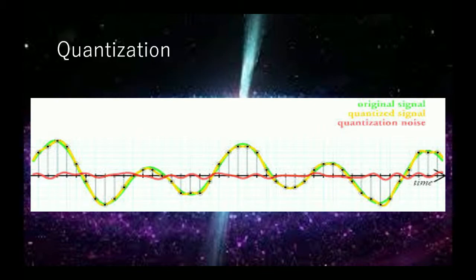There are two types of quantization: uniform quantization and non-uniform quantization. The type of quantization in which the quantization levels are uniformly spaced is termed uniform quantization. The type of quantization in which the quantization levels are unequal, and mostly the relation between them is logarithmic, is termed non-uniform quantization. There are two types of uniform quantization: mid-rise type and mid-tread type.